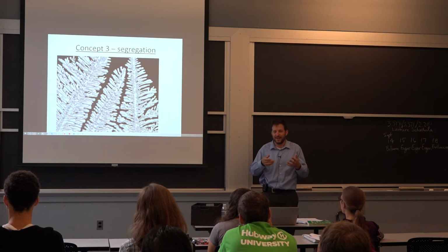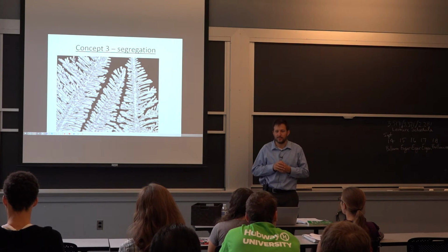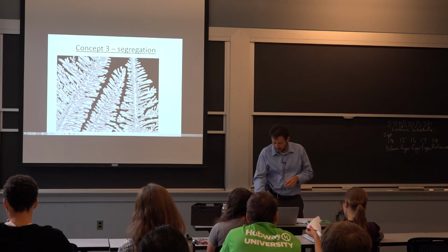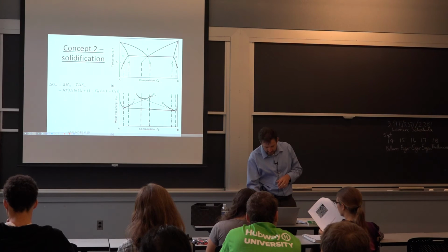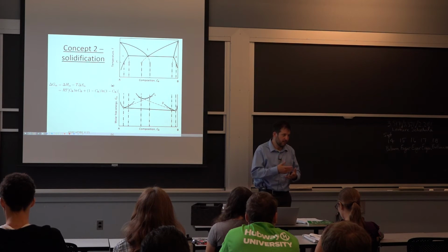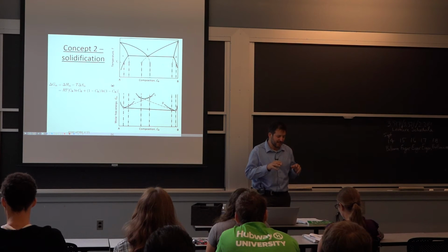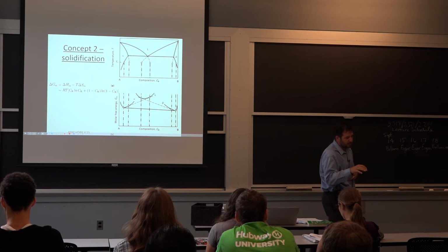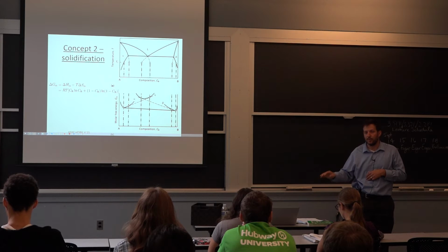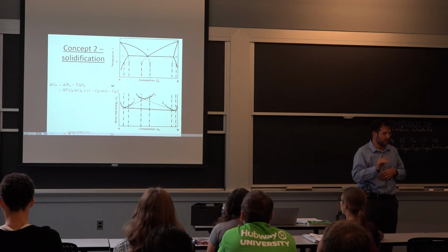It says, okay, I guess I can take you into my crystal, but if I can avoid you, I'll keep pushing you back into the liquid. And that's really what we call segregation. And we'll go a little bit more into the details here: there's a thermodynamic force that drives this that says, you know what, I don't really want you in my alloy. I'm going to, for now, make almost my pure. The system doesn't worry about what's going to be the equilibrium 500 degrees cooler than where you're at right now. So it's all about the best equilibrium at the temperature you're at.